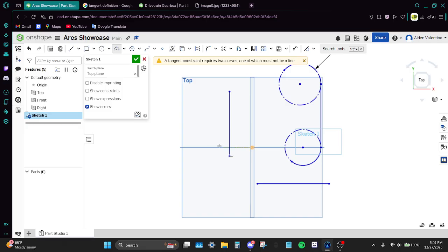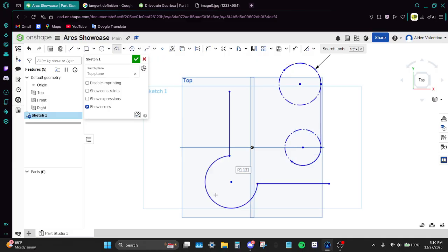This is the most complicated one, I guess, of the three I'm going to talk about: the 3-point arc. With 3-point arcs you set one point, you set the other point, and then the radius of the arc can be anything. If you see that little dot there that's moving with it, arcs are basically part of a circle. So that would be the center point of a circle if we connected our arc to be a circle. We can set these 2 points where it'll connect, and we can set the third point of where the outer edge will be, and that sets our radius.